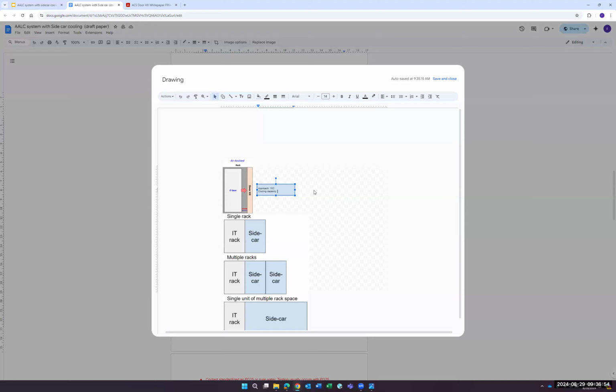The temperature of the air is increasing by the servers. Right. So therefore, it's difficult to compare these two technologies in that way. But yeah, I think for the rear door, if you consider only the temperature before the rear door and the temperature of the water, the power capacity could be 40-45 kilowatts.